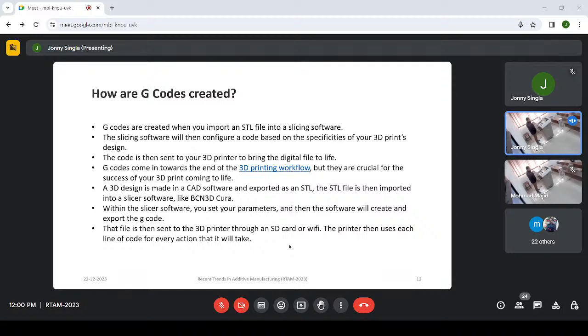According to that height, each layer is cut, and then the directions, or you can say coordinates, are measured, and we connect those coordinates with the help of our G codes. If you have a circular arc somewhere, then we have to use a circular code for that. If we have a linear straight line, then we will use a linear code. If somewhere some material is missing, then you have to use some other code, right? So again, some addition is there in this.